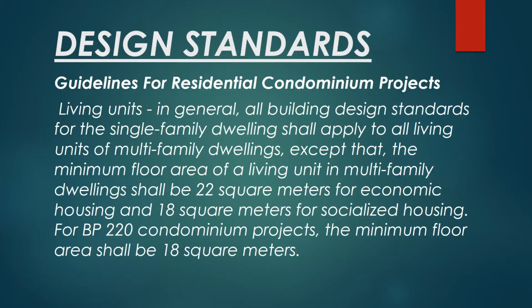For Chapter 3, we have here the design standards. Guidelines for residential condominium projects. Living units in general: all building design standards for single-family dwellings shall apply to all living units of multi-family dwellings, except that the minimum floor area of a living unit in a multi-family dwelling shall be 22 square meters for economic housing and 18 square meters for socialized housing. And for BP 220 condominium projects, the minimum floor area shall be 18 square meters.